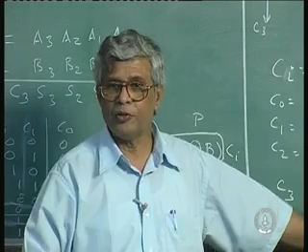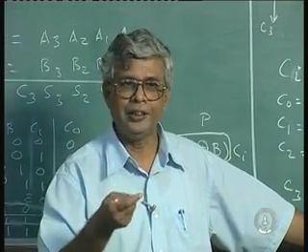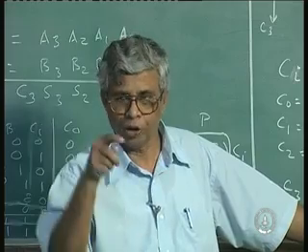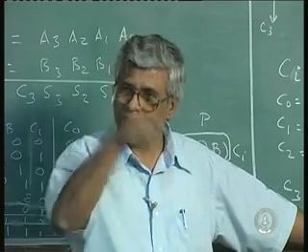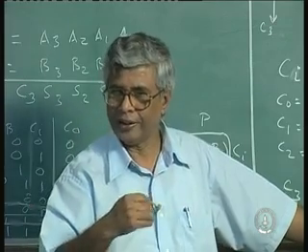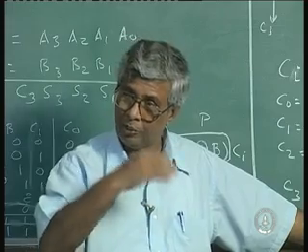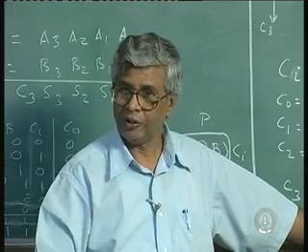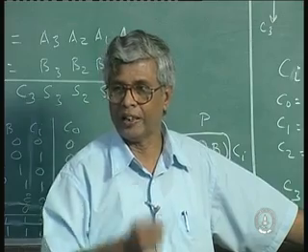The second option is that within that I can do a carry look ahead. I can do a carry look ahead of the 4th stage, 8th stage, 4th bit, 8th bit, 12th bit, 16th bit, and use another carry look ahead logic to generate a higher level carry look ahead. So I can go on doing it, cascading. Carry look ahead can also be done in different levels. I can have a 2 level carry look ahead, I can have a 3 level carry look ahead, I can have a 4 level carry look ahead.